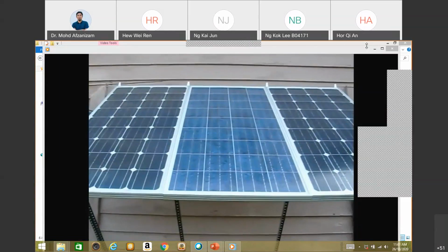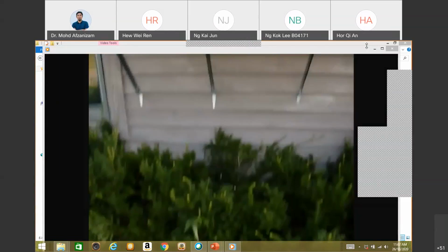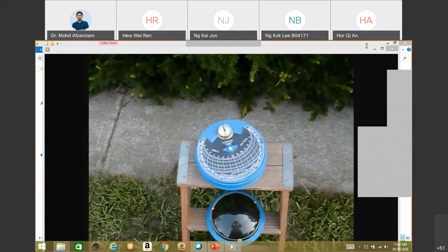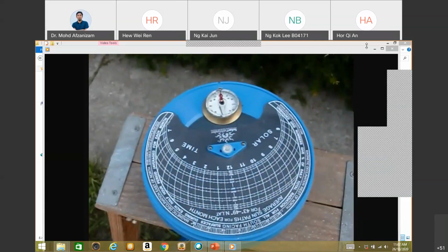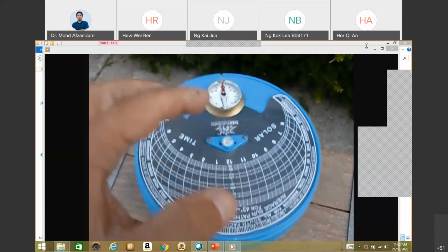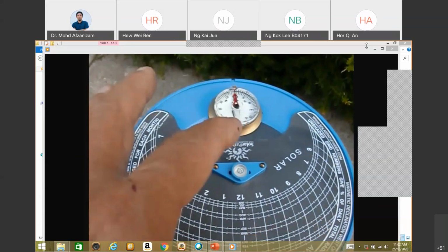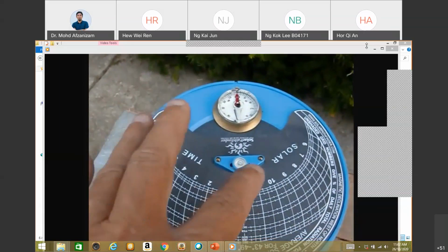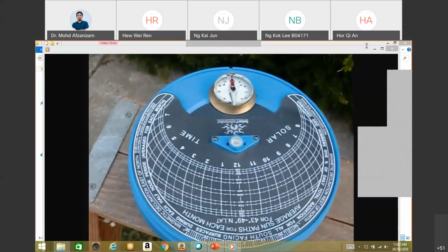All right, so I'm in front of the new panels here, and I'm now going to use my solar pathfinder to tell me exactly how much shading I'm getting throughout the year. Let me zoom in on this a little bit. Okay, so the way this works is you put this grid on here that faces south. Adjust the rotation of this so the red part of the compass is facing due north. And then you also level it with this bubble level in the center. So this whole part of the instrument rotates.